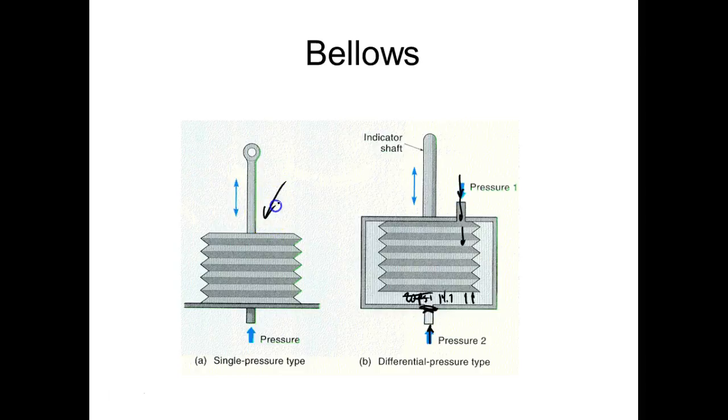The one we got is just like this. So it's got a solid mount. This is relative to atmospheric pressure. So atmospheric pressure would be coming up here and putting 14.7, which would be trying to push it in. And then what we put in here would actually start expanding it when it got above 14.7. So if I set 0 right here, then this would be gauge pressure, right?